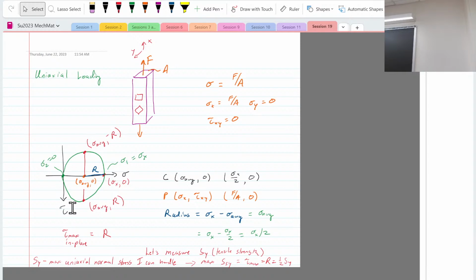It's actually on the slides for you too. So later on, you're talking about max in-plane principal stresses, right? In that case, you take the derivative of the sigma x prime, and then we have these expressions for sigma 1, sigma 2. And also for the maximum in-plane shear stress, you take the derivative with respect to that, and you count x. As you're pointing out, there's a typo there. So let's fix that. There should be no x there.